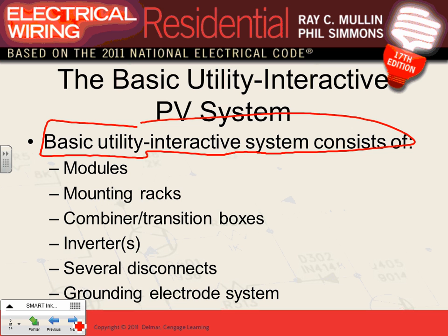They have a bunch of systems. I'll show you the system that they use. But interactive system works only if you have power. If you have power from the grid, they sense that there's power in the grid, they keep supplying your house with solar as long as the sun is there. The minute that they lose power, by UL standard, you have to isolate yourself from the grid so you can't feed the power back to the grid.